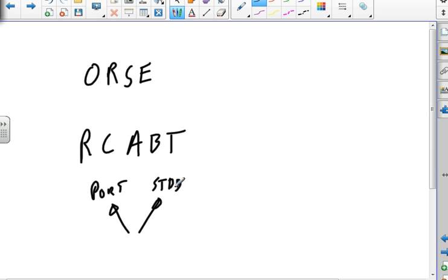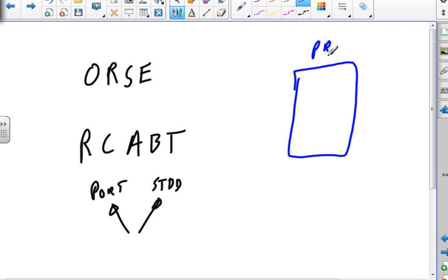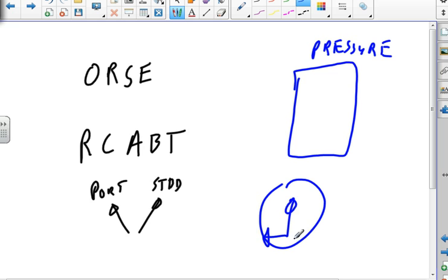Now why do we do that? We manually shift it to the other one. Well, we do that to make sure it works, because if it doesn't work, we better fix it before they show up. All right, so the mid-watch does that, and pressurizer level, which is an indication, goes away. That's my normal indication. It's now pegged over here at 0.